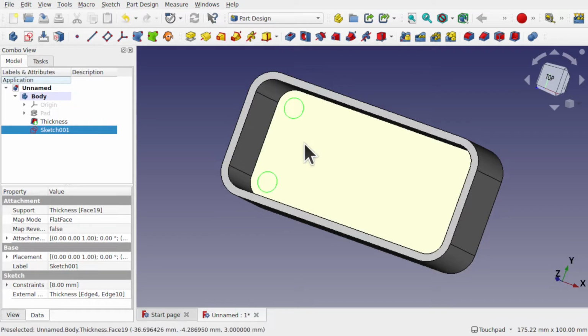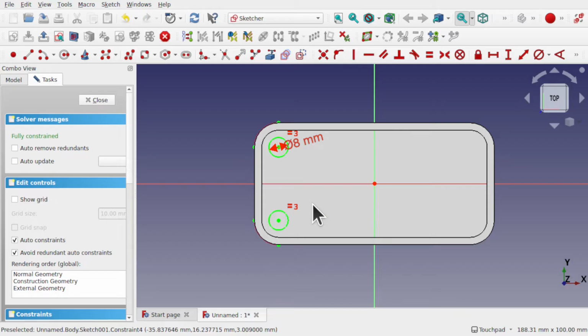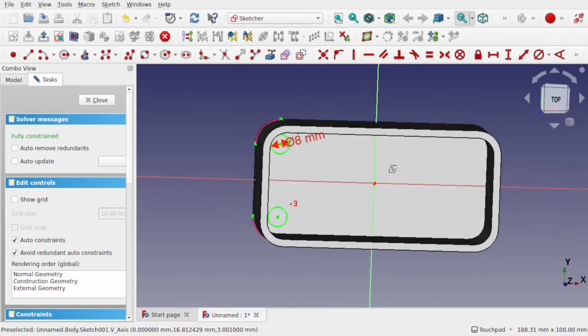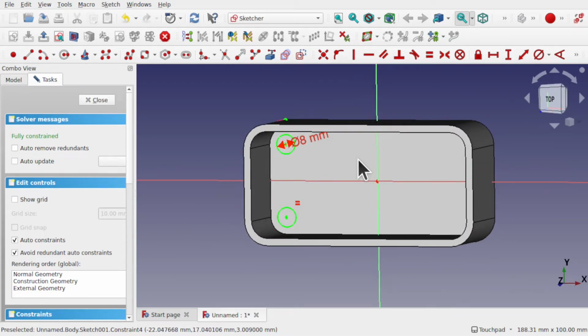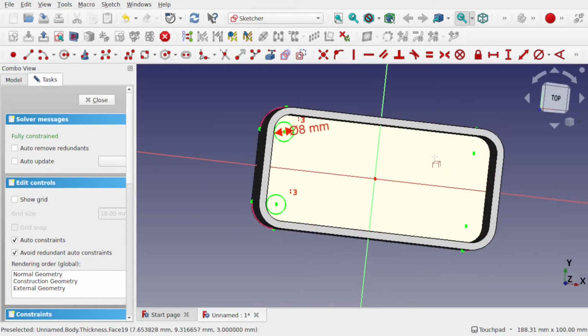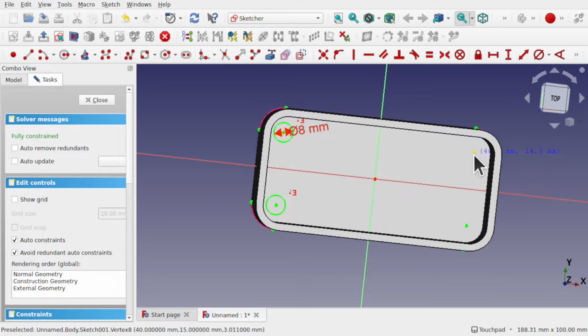So we're only doing one side because I'm going to mirror it over the other because this is symmetrical, so I don't need to sketch those both into place. Now I've got those in there, I could use a symmetry against this with a mirror because we have a symmetrical model. But for the amount I'm doing in here, I might as well just come back in and import these curves and just add to this sketch. So I'm just going to import the curves here and just do the same, add some circles in here.